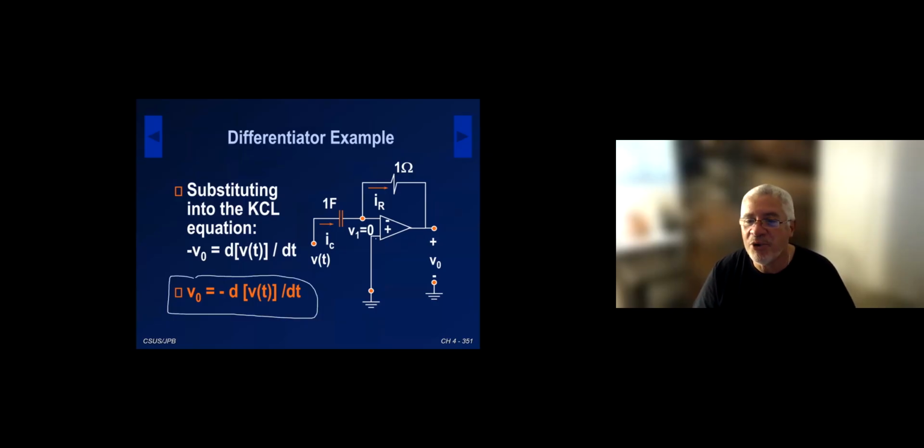The output of this circuit is a derivative of the input. Actually quite cool to have that. Quite cool. So you can see how very simply you can make really more sophisticated circuits than what we were able to do with just a basic resistor. In this particular case, we can essentially create a simple circuit that gives you the derivative of a function using an op amp.